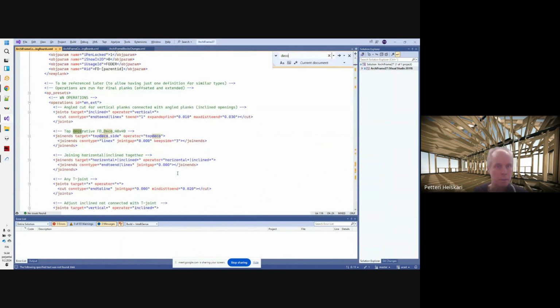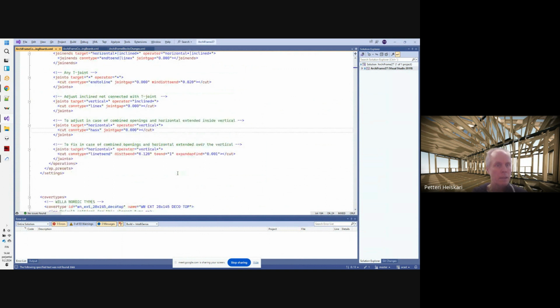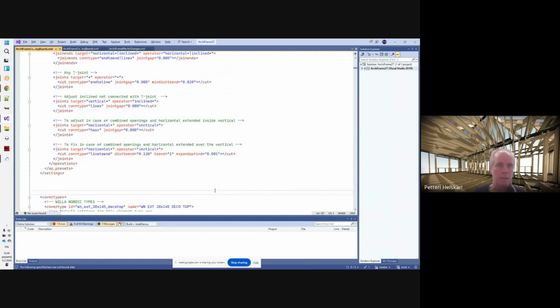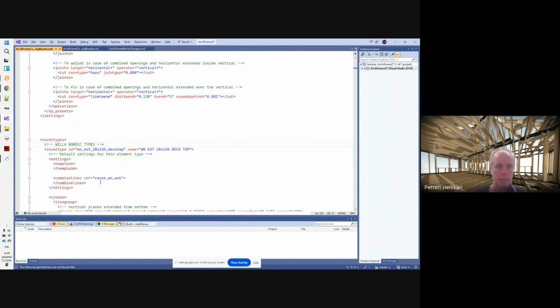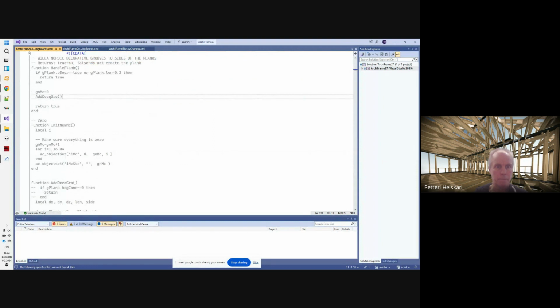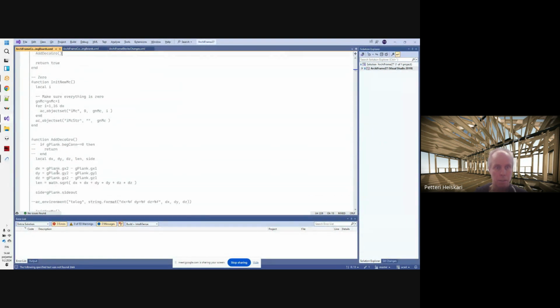It was decorative top. So this ArchiFrame covering boards contains XML, and then to do fancy things, you can include a Lua script, and in the Lua script you can make this. You can check the jump depth, and then use different material IDs depending on how deep in the wall the window is. And this example makes the decorative grooves.